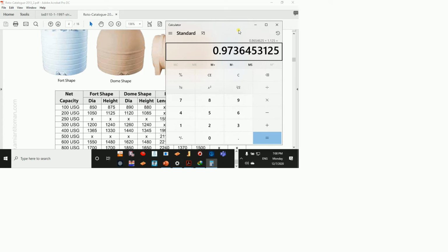For example, this was an open area. When I took it, it was an open area. Nobody was expecting that I'm going to put a wall here. But the designer needs to take that into account. So normally they will try to calculate the maximum possible weight of walls, and they will divide it among the area, because you cannot have walls all over.